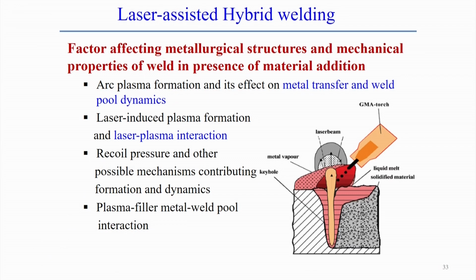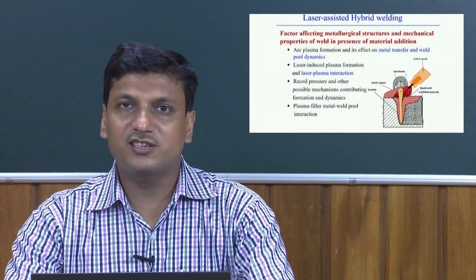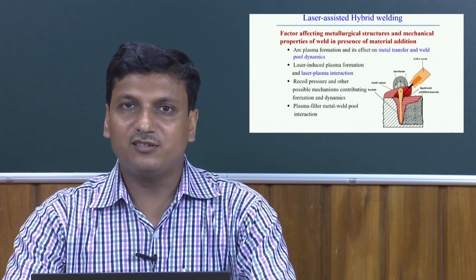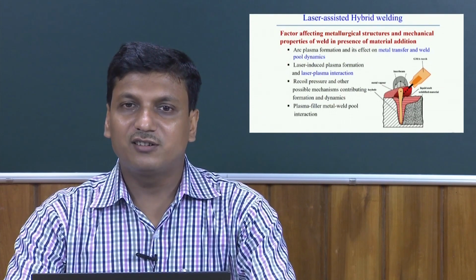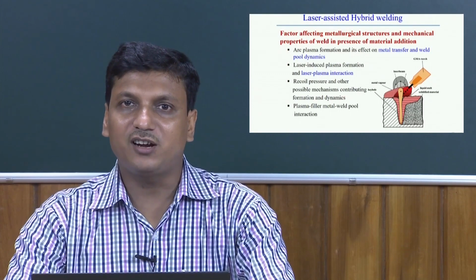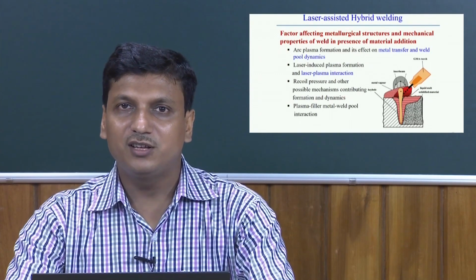Next point is the recoil pressure and other possible phenomena considering the formation of the weld pool dynamics, basically the influence of any kind of shielding gas that creates more complicacy in this process. And of course, finally, the plasma, filler metal and weld pool interaction also becomes another factor of complexity, and it is difficult to analyze all the effects of the individual phenomena in a straightforward way.